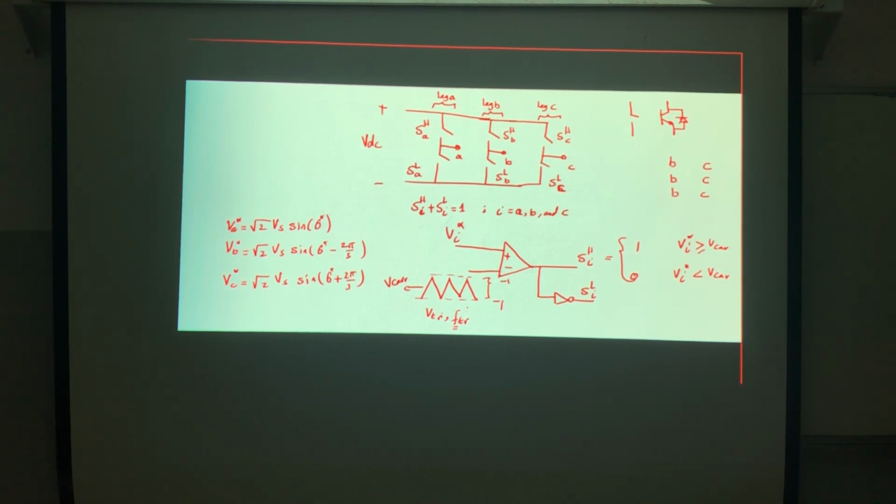The frequency of the carrier will decide the harmonic content. In general, for the inverter, we have conduction losses and switching losses. If I'm increasing the switching frequency, I'm increasing the switching losses, but I'm reducing the conduction losses. This is in terms of the losses. But this one will also decide something very important: the speed of the controller.